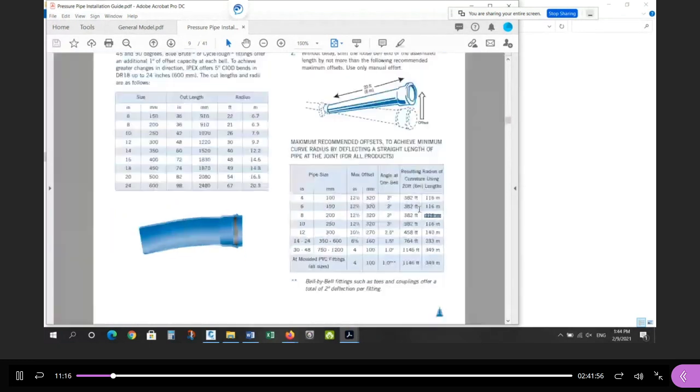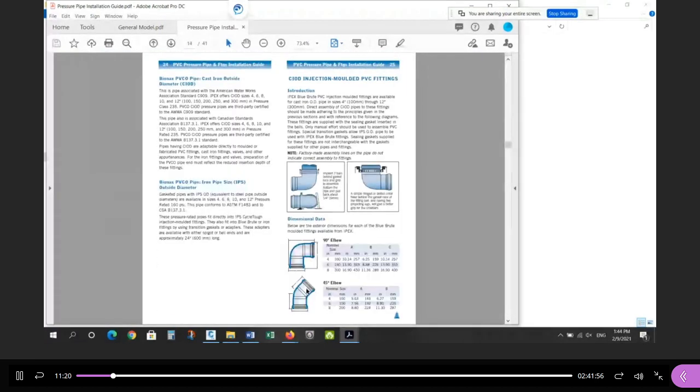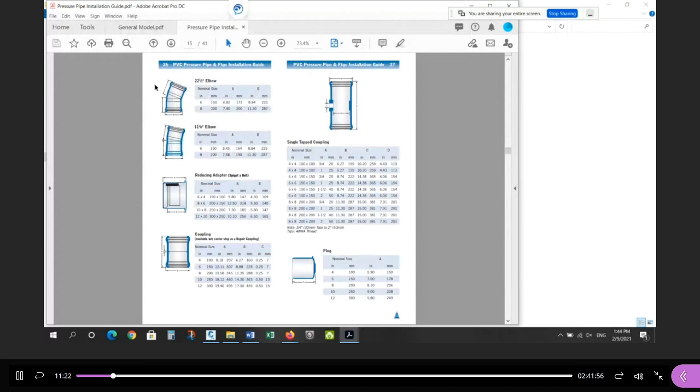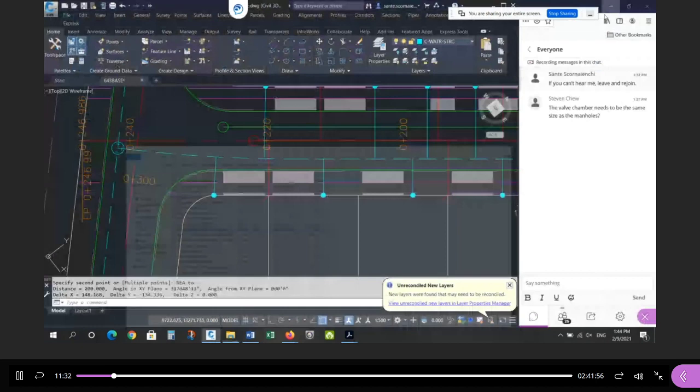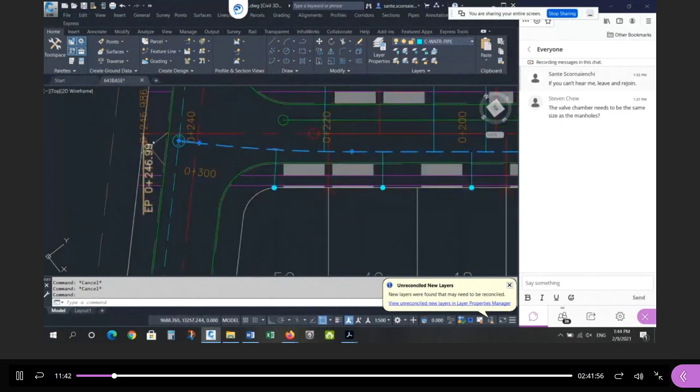Okay, so then I don't have to buy a 90, a 45, a 22 and a half, or a 14 and a quarter elbow. So I don't have to buy an additional piece. I can just kink the pipe along and it should work. Okay, so that's how I achieved that. And again, a lot of people were asking me about this, and all I said was, when this pipe meets this pipe, make sure in here it's exactly 90 degrees. So that's what I did.